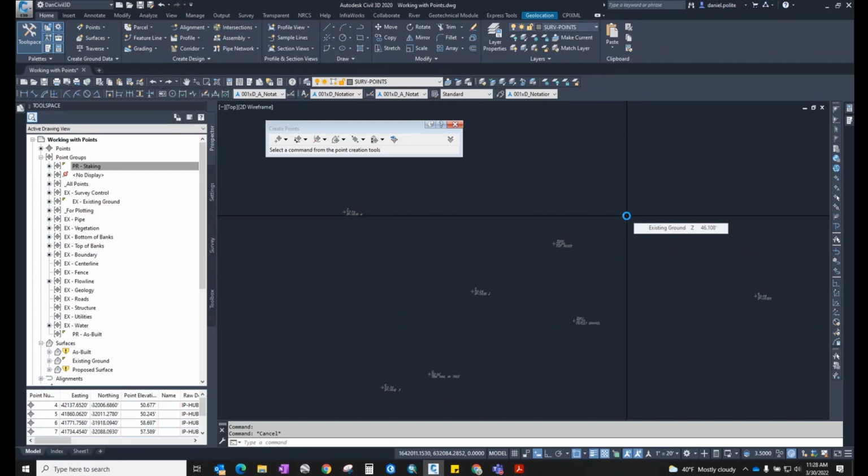And it doesn't have to have an elevation. You can adjust that on the fly with your data collector. So if you put your silt fence at elevation 0, you're really not setting an elevation for your silt fence. All you're setting is the location. You just want to know that the contractor needs to put silt fence down along this bottom. So you're just putting those shots in there along that silt fence location, and not caring about the actual elevation of that silt fence.